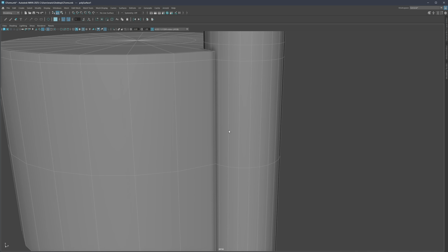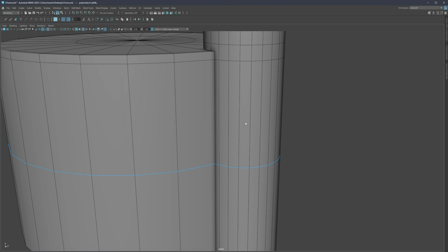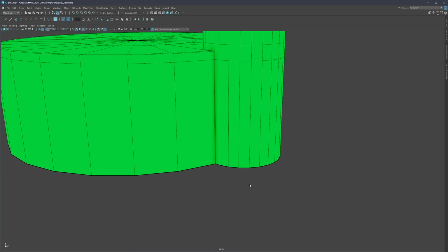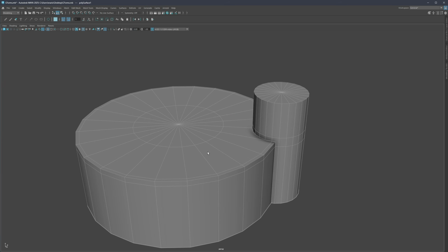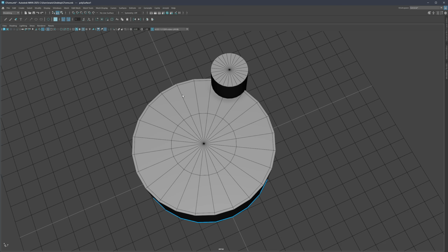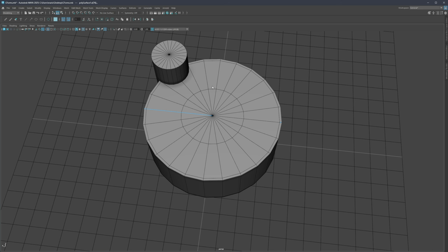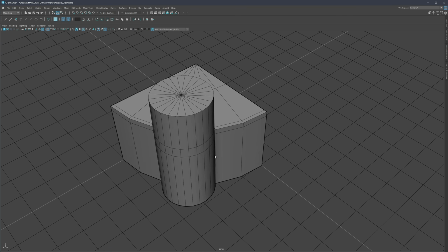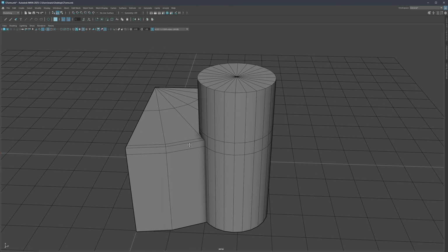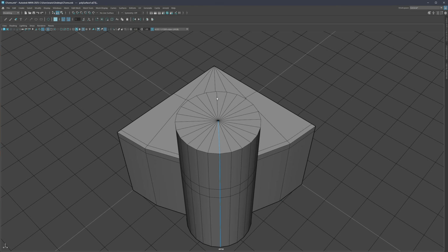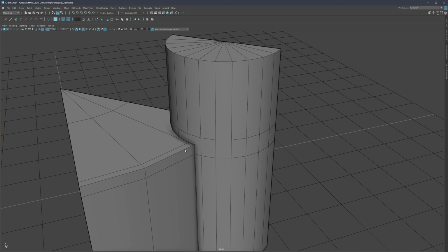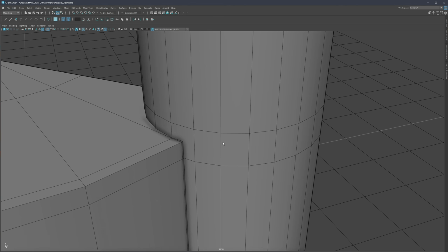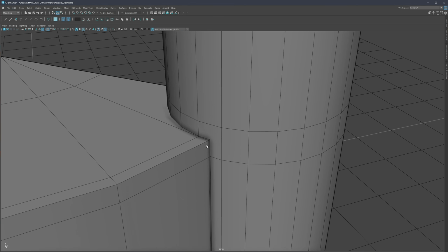So what is now left is connecting or detaching the bottom. And if you see this green thing happening, that simply means there is no material attached. So we're just going to attach the material. And also what we're going to do is cut this and cut this. So detach and delete. Now we can work only on this part right here. In addition, we can also cut this in half, and we only work on this half. Again, just simplifying everything that we can and working on that small piece.